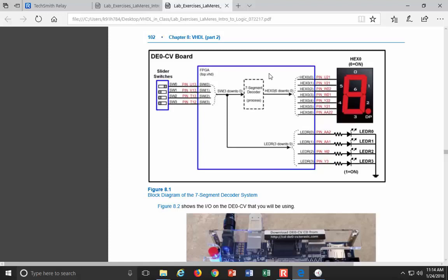That's the common naming convention for a real synthesizable design that goes at the top level, meaning top as in its ports are the real world. So the ports that come out of that FPGA are going to drive LEDs. They're going to drive connectors. They're going to receive buttons. They're going to receive slider switches. So those ports are real. That's not to say you couldn't have a subsystem inside of it, but just think of top as you are the top of that FPGA and you're talking to the real world.